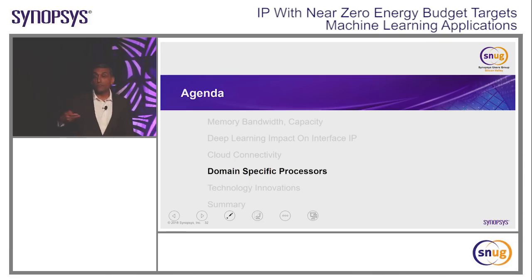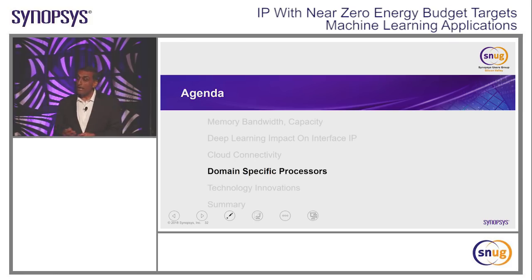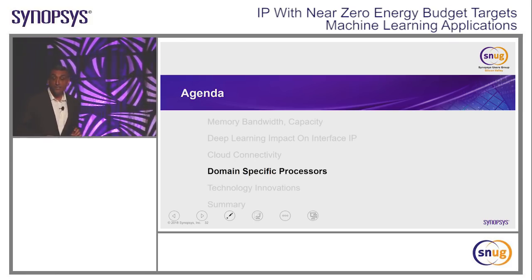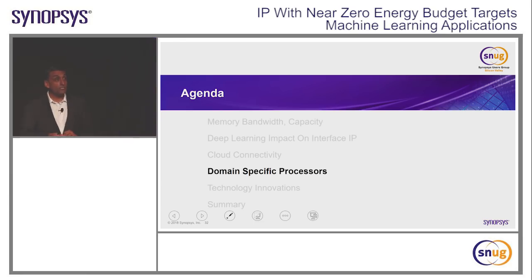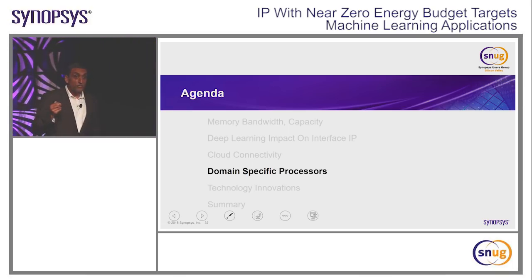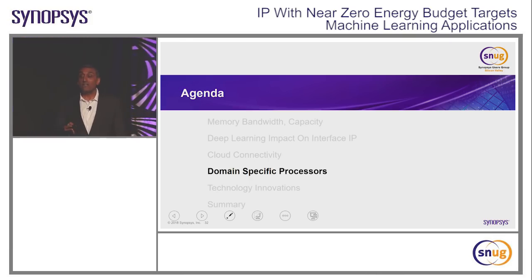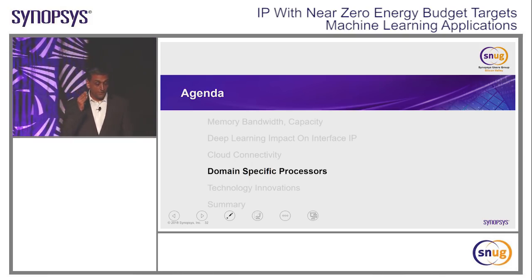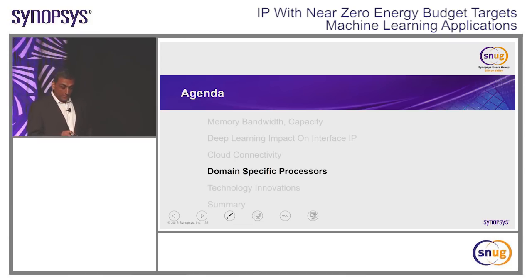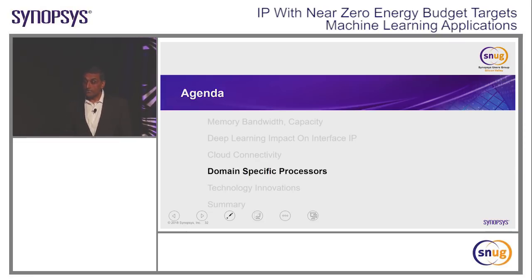It's a fascinating book, especially for me, because I've been educated on von Neumann architectures, and this actually does a lot of great comparisons of, say, x86 with the A53 and Google TensorFlow type architecture. So thoroughly worthwhile going through that book. What Hennessy talks about is the fact that all the traditional scaling laws, Moore's, Dennard, Amdahl, are slowing down. This means you have to do a few tasks, but do those few tasks extremely well. So it's all about focusing your processor architecture on a few simple but very high-quality tasks.